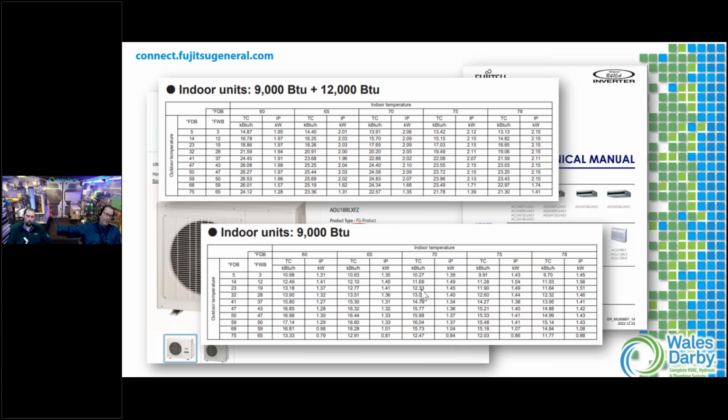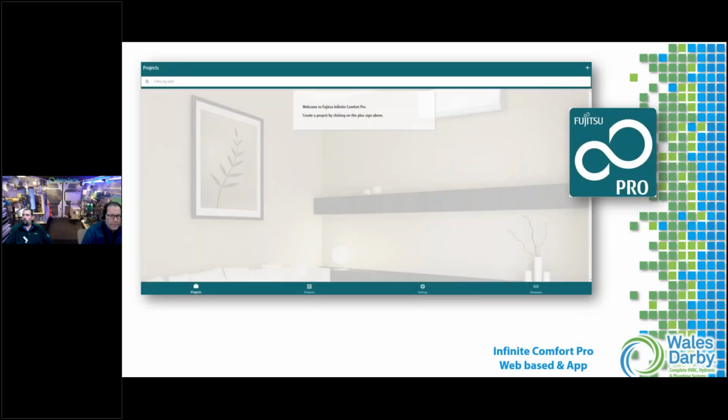So now I'm going to shift and move more refrigerant that way. Speed that up. Move more refrigerant EEV-wise. That's the nice thing: I don't think I've ever seen a system where every zone is under full load, and that's what's nice about being able to hook up this 125%, 130% connected capacity.